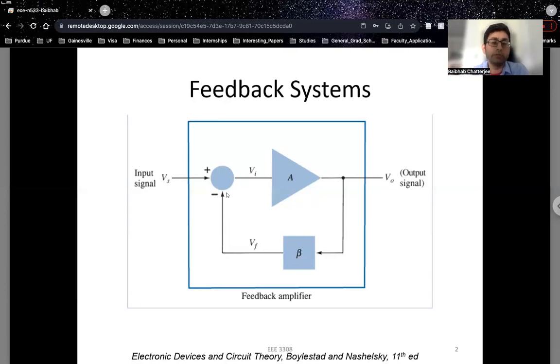We generally talk about phases: if your input phase and the feedback phase are in the same direction, and you are adding those up, then it's a positive feedback. If they are in different directions, then it's a negative feedback. But that is a more strict definition. This definition is much easier for you to comprehend at this point, that if you see a negative sign over here, most likely it's a negative feedback, because you will not assume the phase inversion over here in many cases.